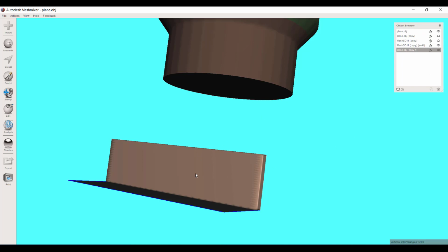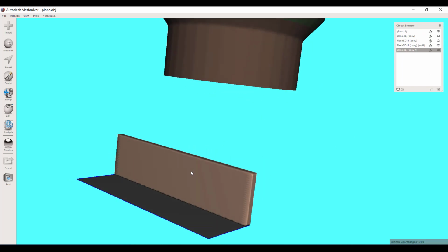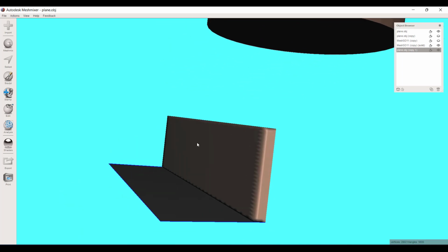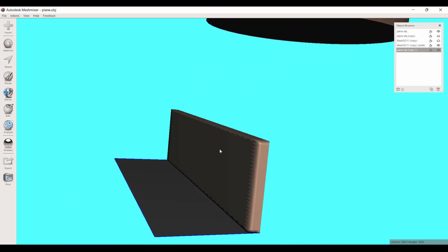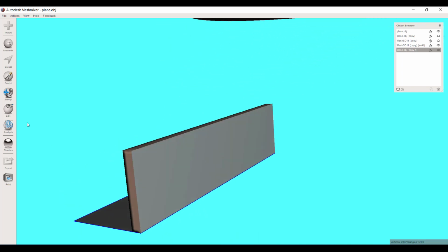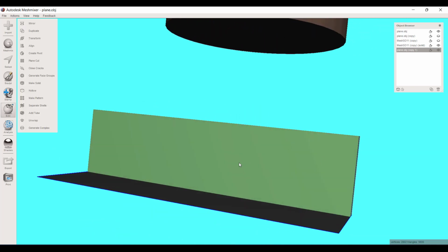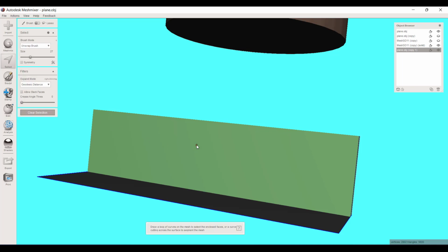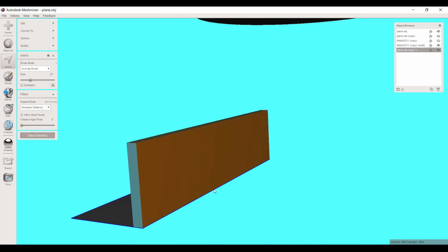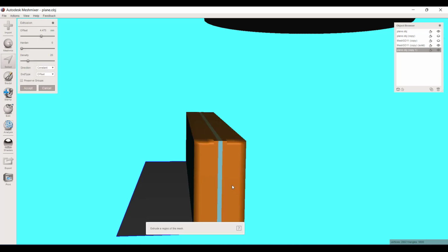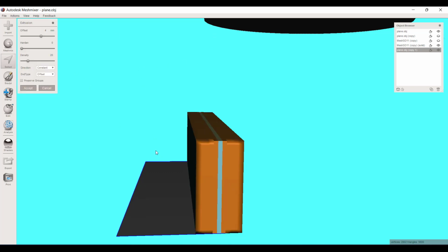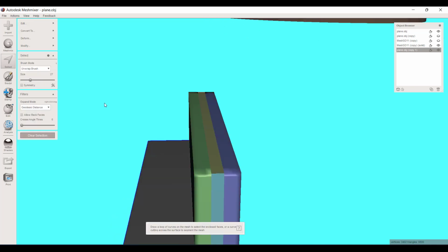All right, I turned off the tank wall, and this is the duplicate of it. So if I wanted to come off 4 this way and 4 that way, again, let's go back to generate face groups. Those are sharp edges. We're going to get a single face group here. Let's click this one and that one and hit D, that's extrude, and let's give it 4 millimeters of thickness. Okay, and then I'll accept that.